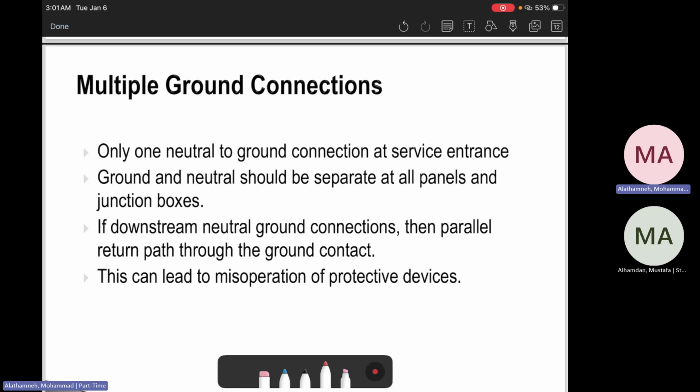This means you can have currents on things that should never carry current in normal operation, like grounding systems. In other words, this can create current into the ground, which is something undesired. Touching voltage on metal parts will be very dangerous because there is ground current on the ground, or it can create strange noise problems or other challenges. In many low voltage installations, RCDs are used in homes and offices. Multiple neutral to ground bonds can cause a continuous leakage current path and lead to random RCD trips, and people then bypass the RCD, which creates a safety hazard. So understanding this will prevent a very real bad practice.